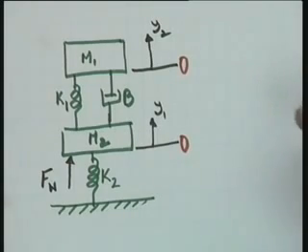So, under that equilibrium position or zero reference position, you will note your springs and dampers are not in the relaxed position, they are getting the gravitational force on them. However, the corresponding position is declared as the zero position of the automobile and the wheels. So, with respect to this position, naturally the model does not use explicitly the gravitational effect, because it has been accounted for in our definition of zero reference.